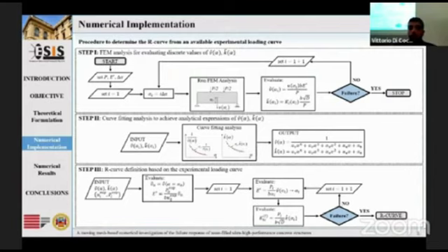Step one performs finite element analysis to calculate load, midpoint deflection and stress intensity factor as a function of the relative crack depth by varying the latter in a discrete manner after assuming a constant depth increment. For each crack depth, the values of the related shape functions V and K are found.